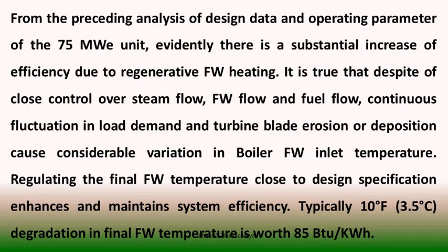Evidently there is a substantial increase in efficiency when we are utilizing the regenerative feed water heating system in its full potential, and when we have close control over steam flow, feed water flow and fuel flow. Continuous fluctuation is there in the load demand, and turbine blade erosion is also there.